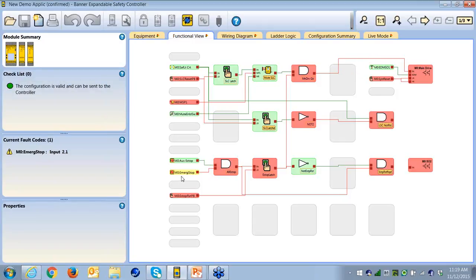There we go. I forgot to turn it back on. Even when I hover over this particular error, it again shows me that it's error 2.2 and an emergency stop. The reason it didn't show up before is I had a dynamic failure. I just pushed one of the two buttons that simulates that e-stop, and released it, and that caused the error to go away. I had to put in a hard failure.